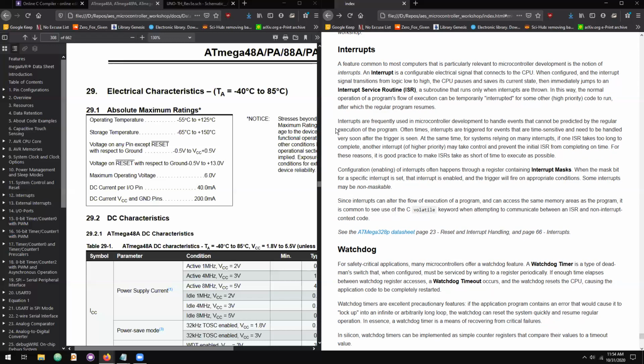The alternative to doing that is polling, spelled P-O-L-L. When you poll a specific piece of information, like a variable in memory, or the pin level in this case, you continuously try to read its current state.